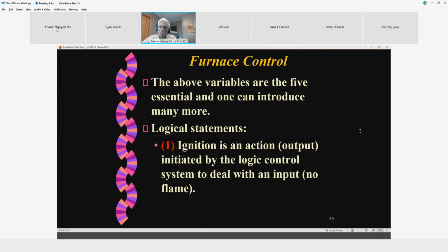But that problem is completely taken out in the high efficiency furnace, where the flame always requires a good amount of oxygen or air to burn. So there is a separate intake which doesn't get mixed with anything else. It doesn't go into your distribution system at all. It comes straight to the flame and then goes out as exhaust gas.